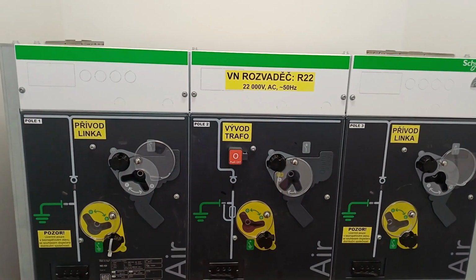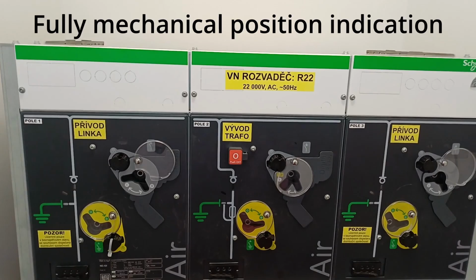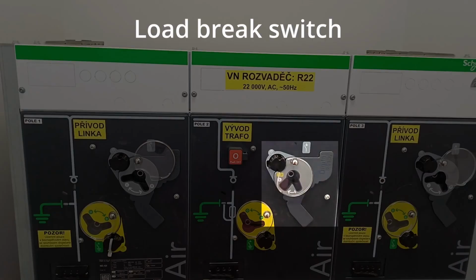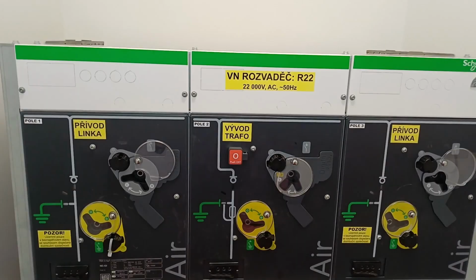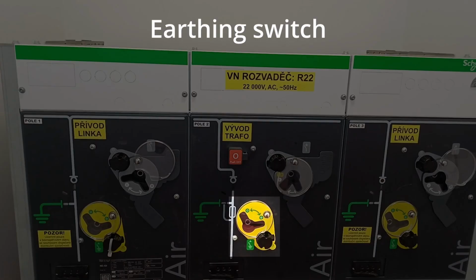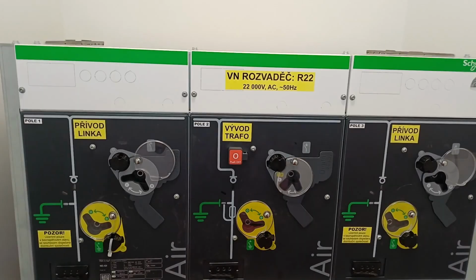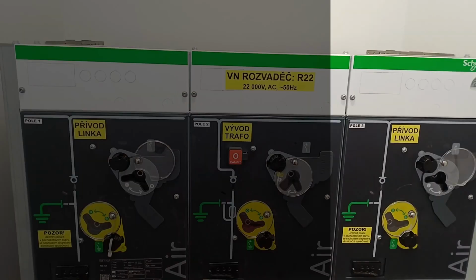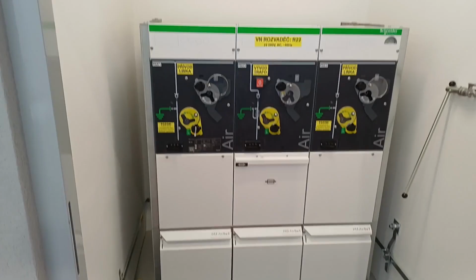These are switching devices. The system typically includes circuit breakers, load break switches, and earthing switches. Each of them has a different role. A load switch isolates equipment. A circuit breaker reacts to faults. The distribution network is often looped. That means power can come from multiple directions. And that significantly improves reliability.